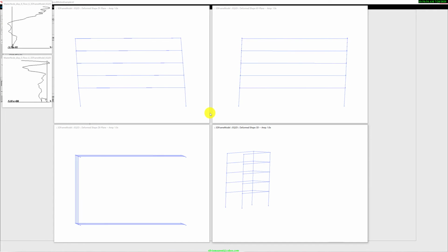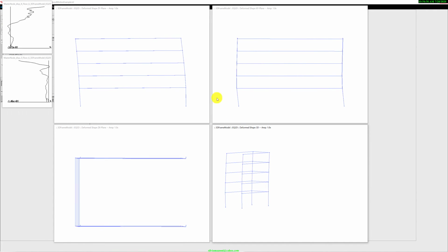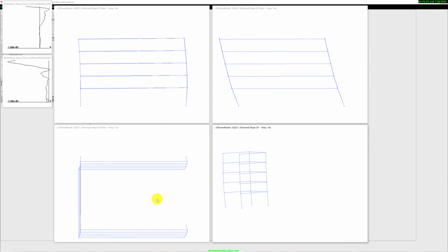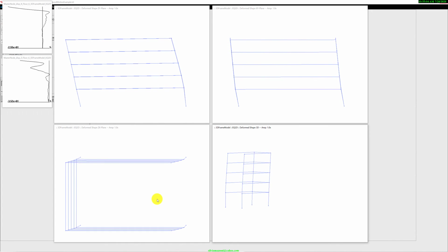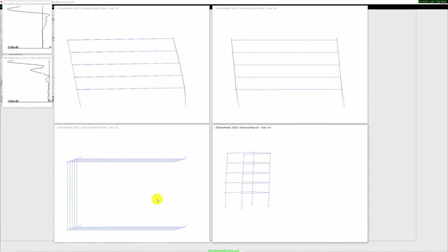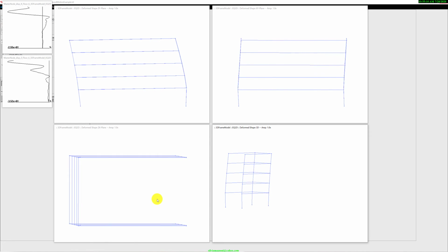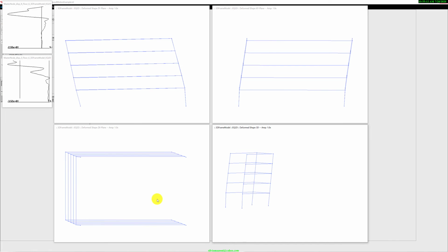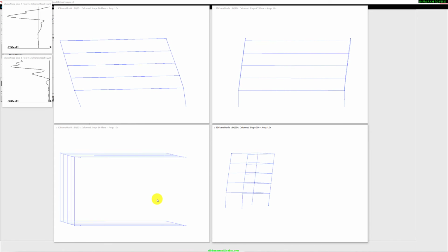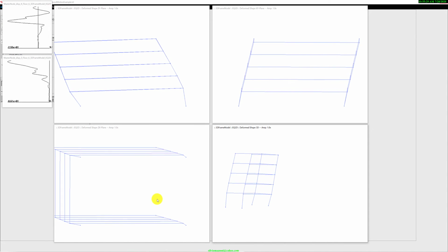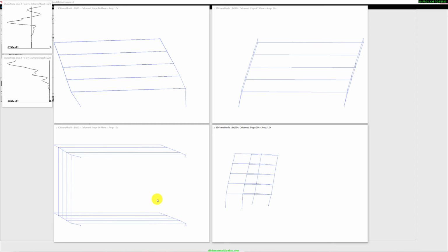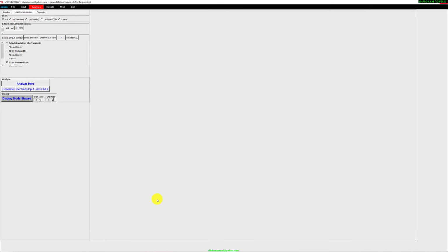You can see the deformations in the 2 directions, as well as this planar view here. The 3D frame is doing a much better job with the earthquake ground motions. But let's see how far it's able to go. We did scale these 5 times. It's made it that far and ran into problems. Let's see what it gives us from the OpenSees output.